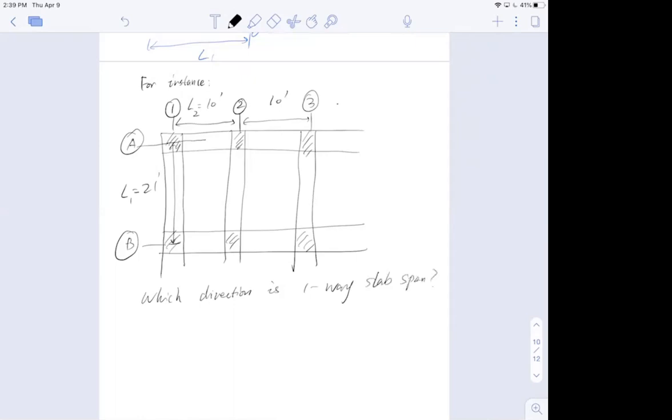And then I'll ask you, if the live load equals 150 pounds per square foot, and the slab is normal weight concrete, f'c equal 4 ksi, and you're allowed to use grade 50 ksi steel, design reinforcement for it. So this will be a typical problem I'll give you.